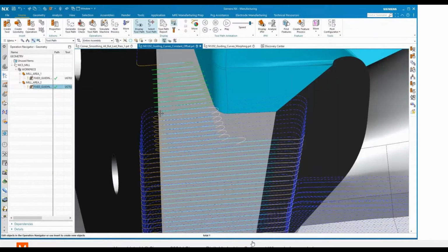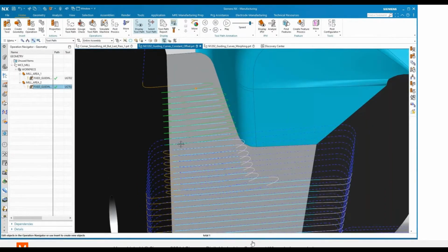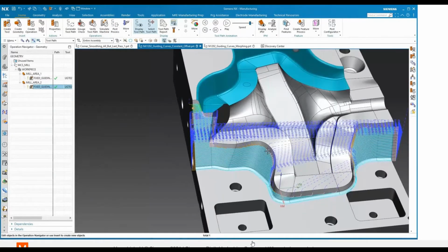As you get to a shorter distance, it's still doing a rapid traverse, but now it's doing a tangent move, so it's not returning to some Z-plane, it's just doing more of a direct motion to get back to the beginning. And for an even shorter distance, there is no rapid. It's using the green step over feed rate to just quickly feed back to the beginning and do the next path. And that's all happening automatically in the algorithm.